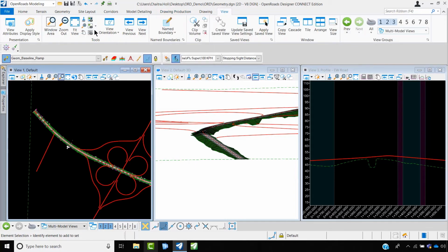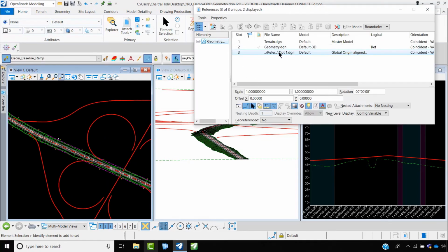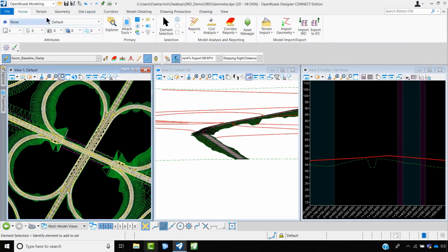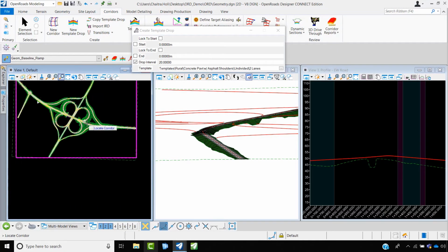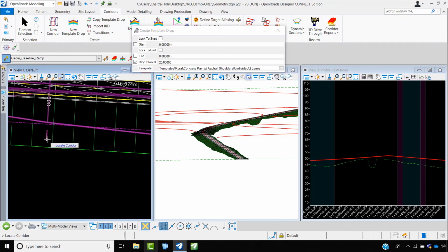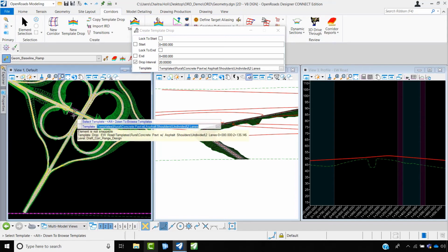Okay, let's go ahead and add even the bridge template. Let me switch it on the extent where I want to add the bridge portion. In a similar manner, go under this corridor. Now add a new template. Whatever you see in these yellow handles is the corridor it created. So for this corridor, I want to add one more template.